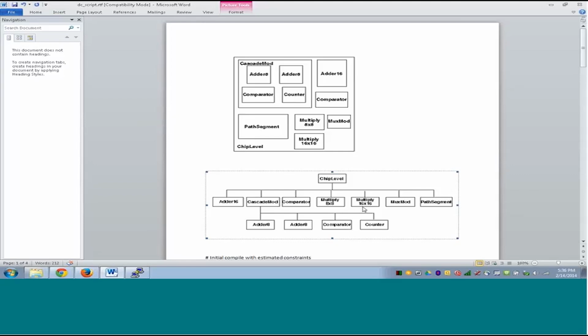So I would still recommend, if you are working on a design that is not a big chip, to think about top down and make sure you have top level constraints available. If top down is not possible, go bottom up, and arrange your stuff in a similar fashion to what is shown by this example.